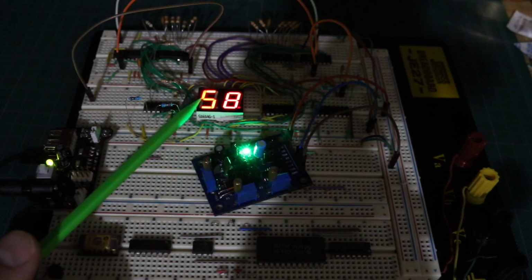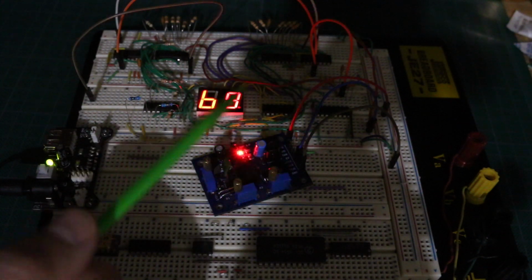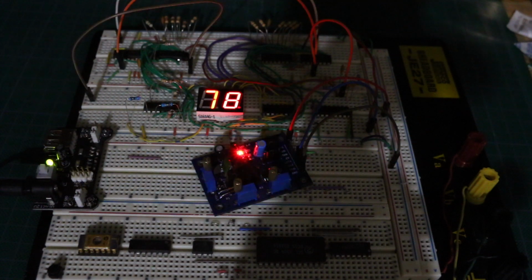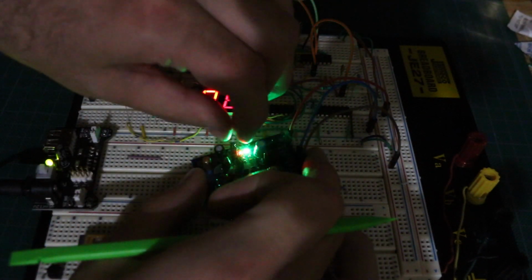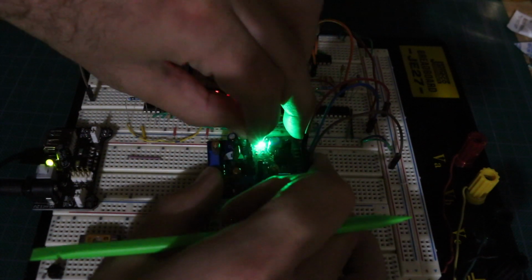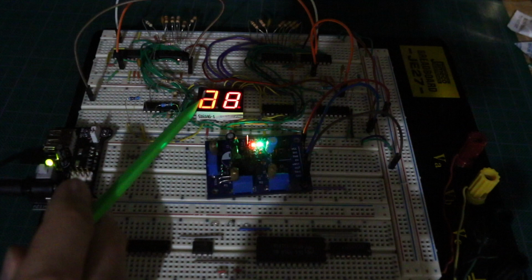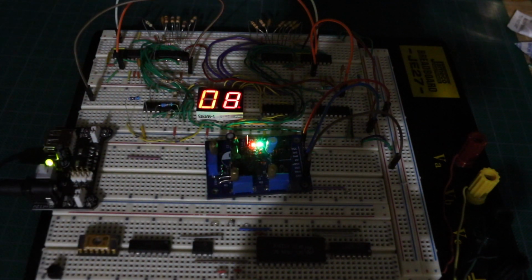So what I'm going to do is speed up the clock so that we can't really see what the count is, but it is going quickly. Then I can pull the clock, and whatever number is showing, that's the winner. So I will take away the electrolytic on the dev board. Now the clock is counting quickly with a smaller value timing capacitor. Now if I pull the clock,